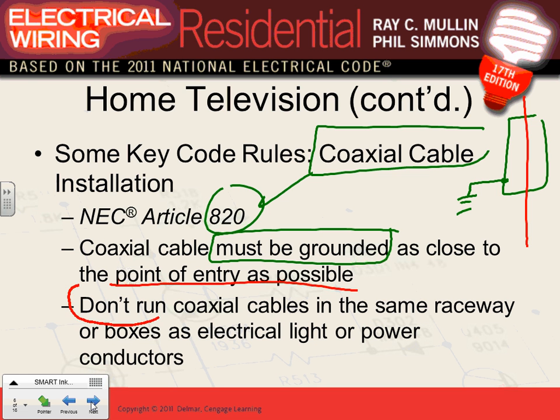Then you take the coaxial cable. Do not run these in the same raceway or box with electrical light and power. Don't we know that? Can you put a coaxial cable in the same conduit or cable or box with lighting, 120 or 240 or 480? No.